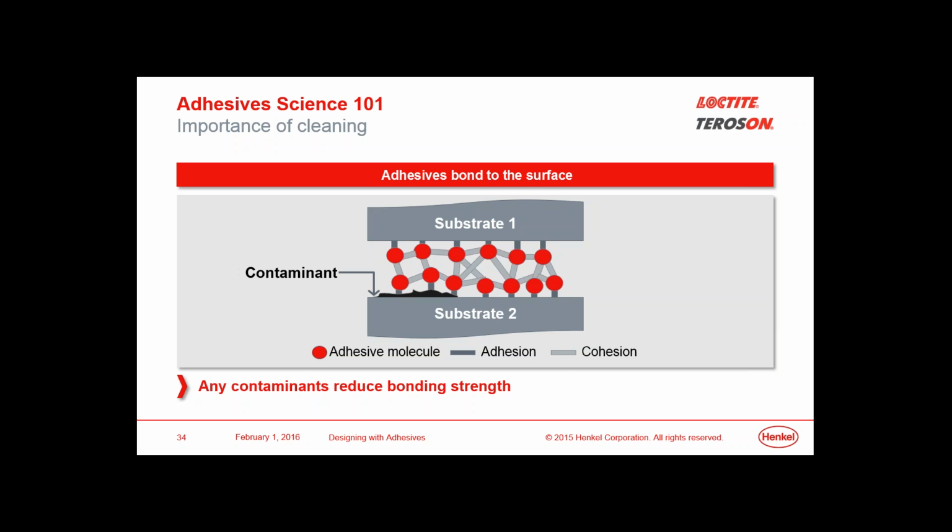And certain chemistries of adhesives are more robust on as-received parts, and some are more sensitive. So again, make sure you consult with your Hisco or Henkel representative to select a proper adhesive for your parts. And it's always good to know what specific parts you're bonding. For instance, before you approach your representative, they'll want to know specifically what type of metal and specifically what type of plastics you're bonding. Instead of just metal or plastic, they'll want to know if you're bonding a stainless steel to a polycarbonate material, so that way they can better direct you. So that would save you time.